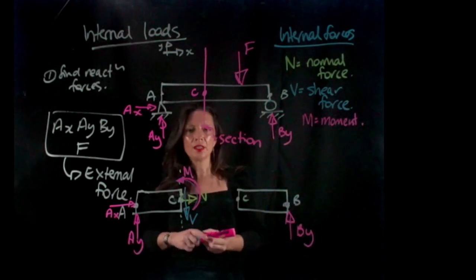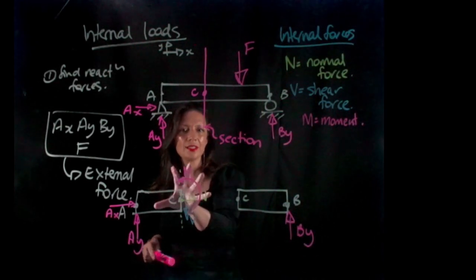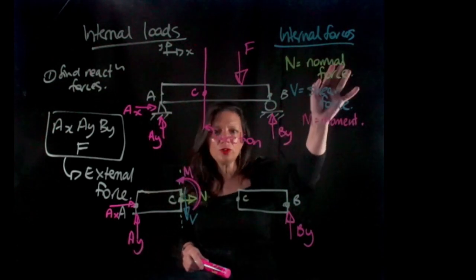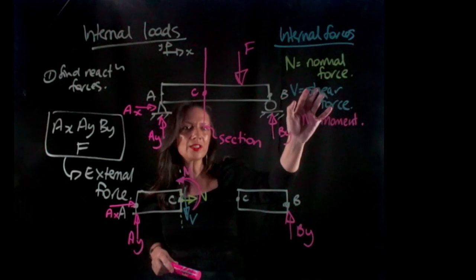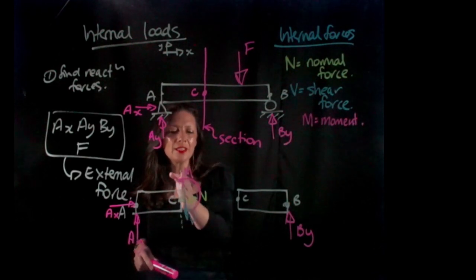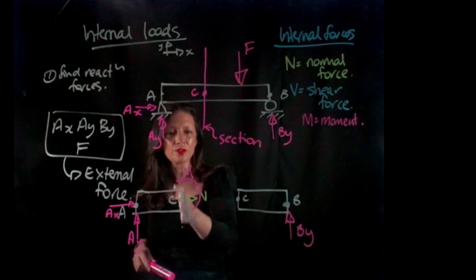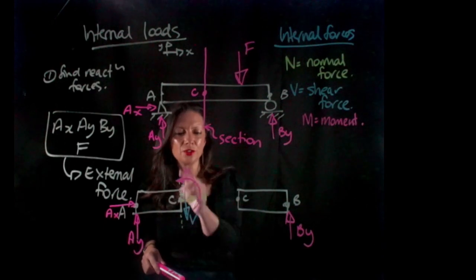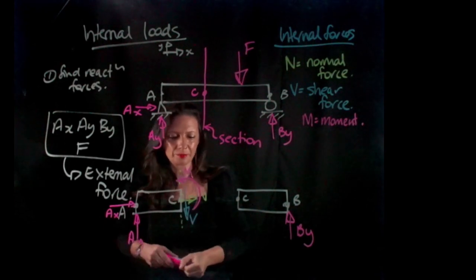Okay, so I have three forces that are internal to this beam: a normal force, a shear force, and a moment. My shear force is parallel to the surface that I have cut. My normal force is perpendicular to the section that I have cut.